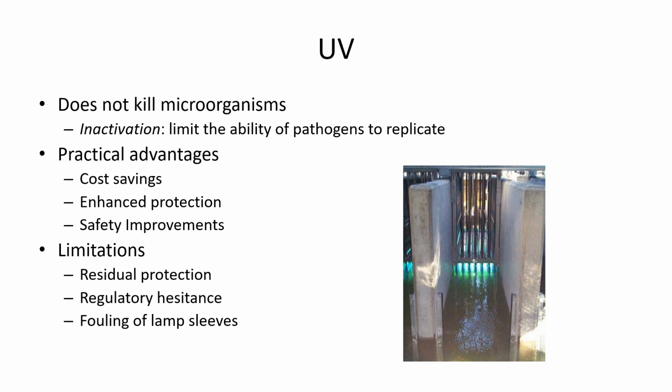So, for example, if you have water with bacteria in it and you chlorinate the water, the bacteria is dead. So what you're drinking is dead, destroyed bacteria particles. They're still there, but they're not going to make you sick because the bacteria can't reproduce inside you if it's dead before you even drink the water. On the other hand, UV does not kill the microorganism, but it makes it so that it's not able to replicate into the next generation.